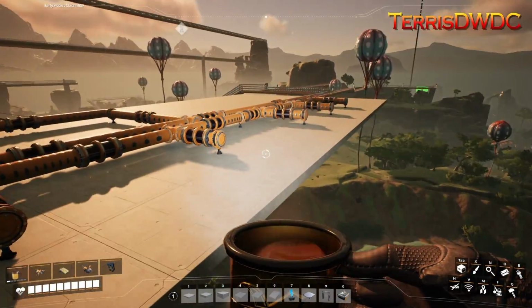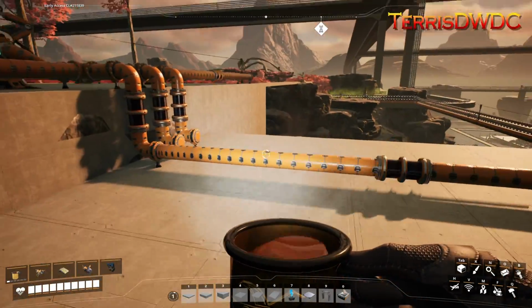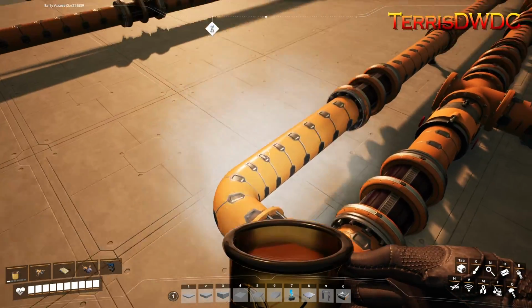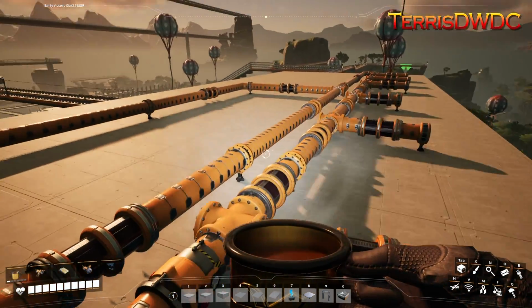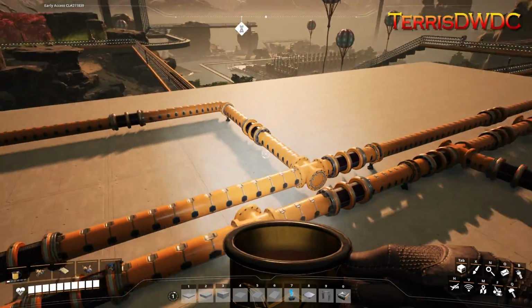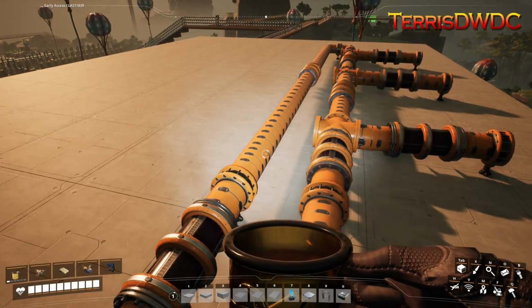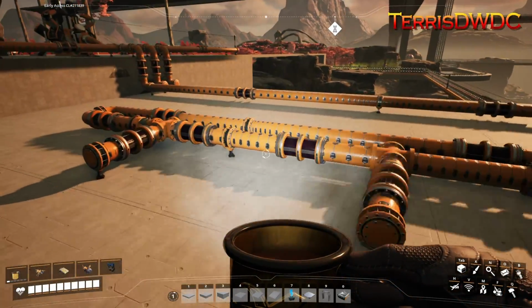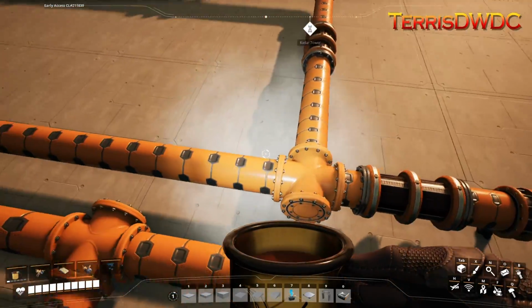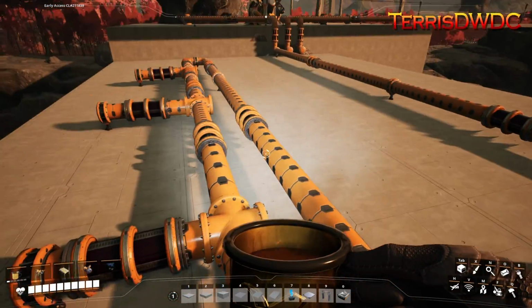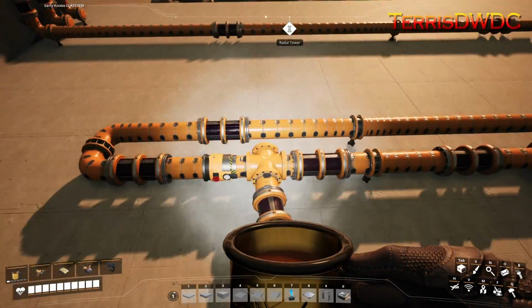See, what would have happened before is if you just brought this line in and just teed it in here, you didn't have this kind of first split that's happened. Let's call it a load balanced manifold. We could call it a load balanced manifold for your fluid distribution. It's not really, but for ease of explanation, it does help picture how that fluid's going to flow.